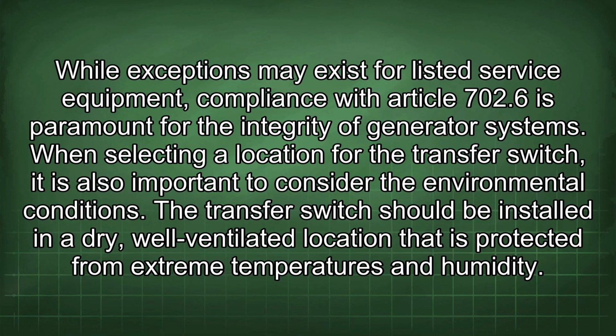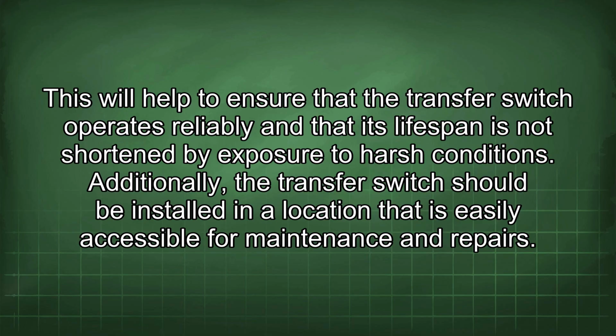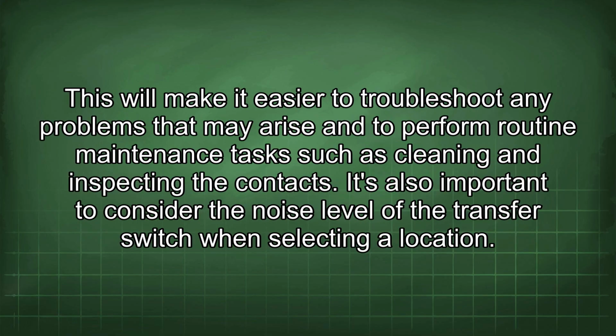When selecting a location for the transfer switch, it is also important to consider the environmental conditions. The transfer switch should be installed in a dry, well-ventilated location that is protected from extreme temperatures and humidity. This will help to ensure that the transfer switch operates reliably and that its lifespan is not shortened by exposure to harsh conditions. Additionally, the transfer switch should be installed in a location that is easily accessible for maintenance and repairs. This will make it easier to troubleshoot any problems that may arise and to perform routine maintenance tasks such as cleaning and inspecting the contacts.